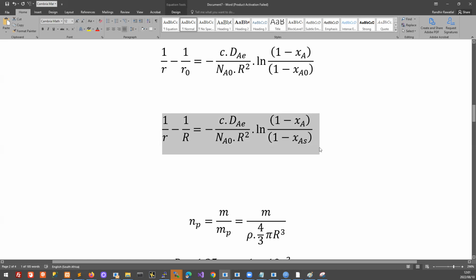That means it still works for all radial positions and all mole fractions. So I can use the same equation to work out my film thickness. I can stick in here a value of 0.99 times the bulk value. So we are given some bulk value, multiply 0.99 by that, and then we can work all this out.